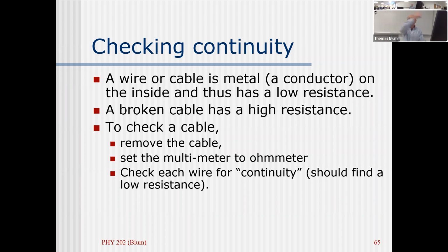An ohm meter often has a 1. If you're looking at a multimeter and you have a reading, it's right justified, and sometimes it just shows a 1, but the 1 really means sort of like infinity on the other side. That is saying I have a high resistance, I have a bad connection. So you don't have to test anything more, it's the wire, it's the connection that was bad.